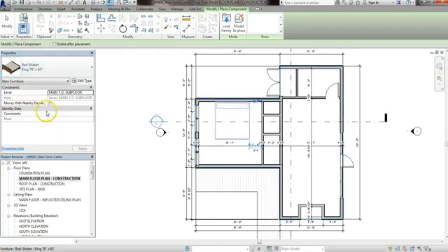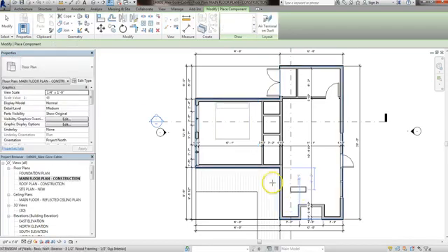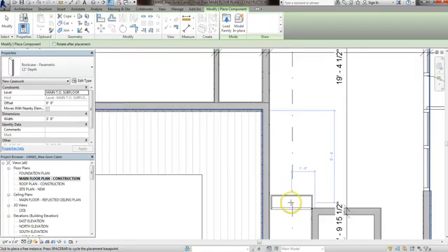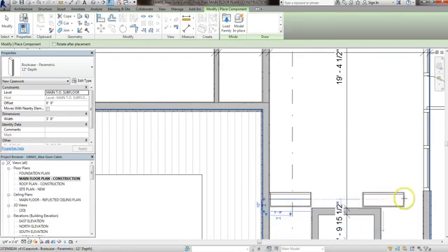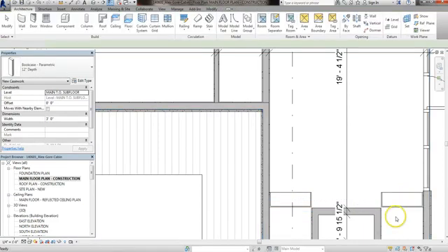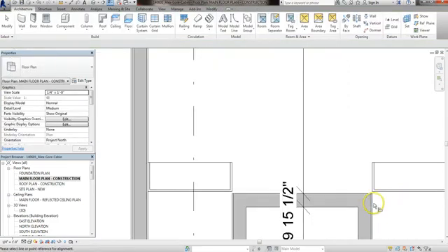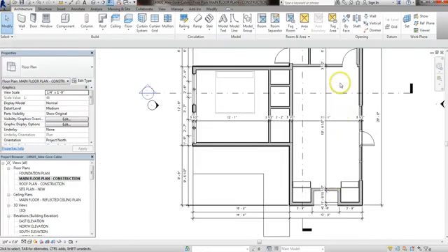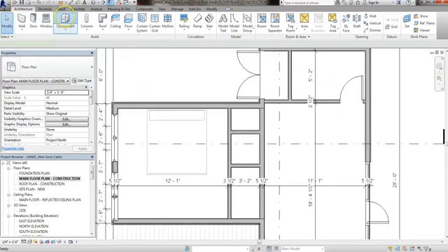Go down, bookcases. The bookcases are going to be over here. I think that side's the outside. You actually have to have in more walls to place these, to line them up. If they're not lining up, you can hit AL for align. Click on what you want it to align to, then click on the object. And the same is true for your kitchen. So they're under components.